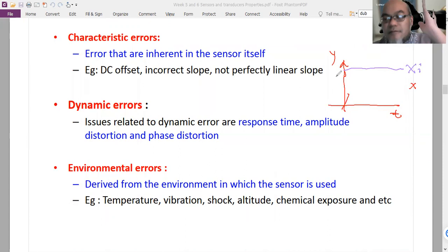So this is a step value we put to the sensor starting from t larger than or equal to 0. The sensor reading will try to follow this, for example like this, until it reaches some steady state value of y output. The time to reach 63.2%, remember the first order, if it is first order, the value of 1 over e is defined as the response time.